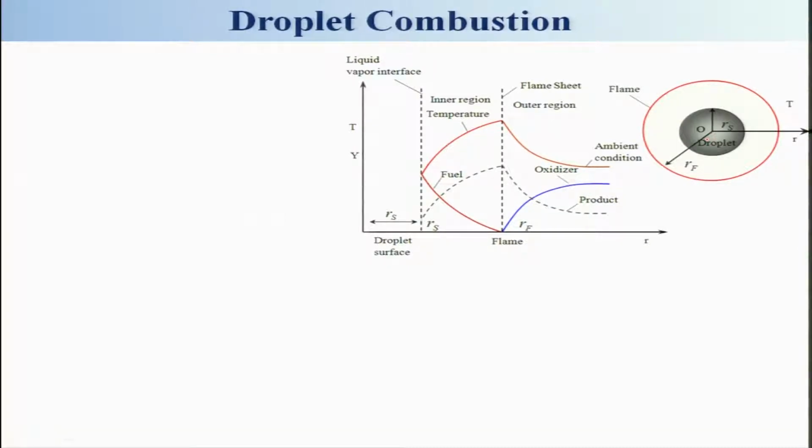Force convection condition, if you look at any practical combustor, will be force convection, because the flow will be coming and the droplet will be there. But for a single droplet, certainly no, you will have to conduct an experiment to understand the process. An array of droplets will be there and each droplet will be moving with its own velocity, but also the velocity will be changing across the cross section of the combustor, and as it moves it will also change.